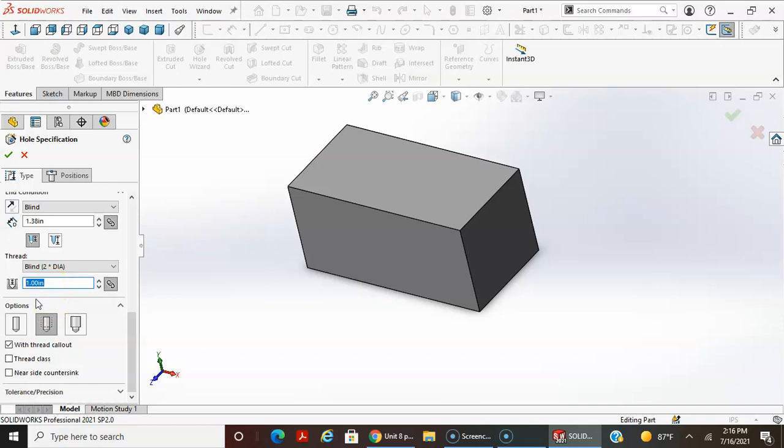So in other words, if you just go 2 times the diameter, it should be enough to apply enough force to keep the fastener fully engaged in whatever application to hold the assembly together. If you go deeper, it's more time consuming, it's more cost to produce, and there's other factors involved. Your fastener size would generally be longer, so it'd add more weight and more cost as well.